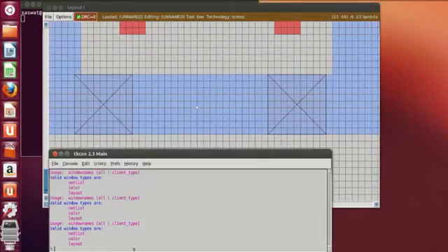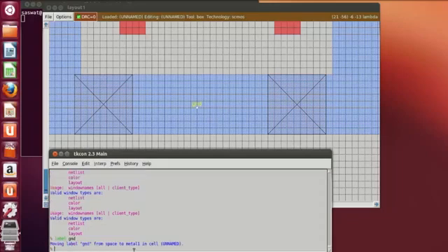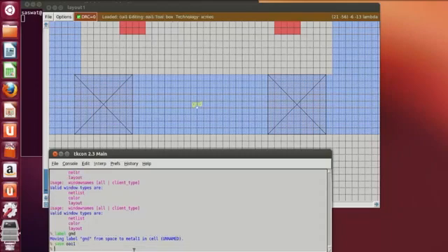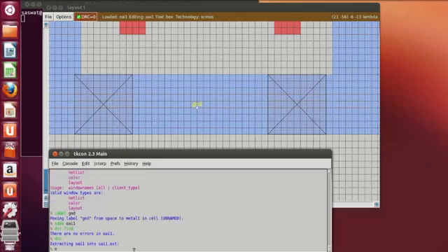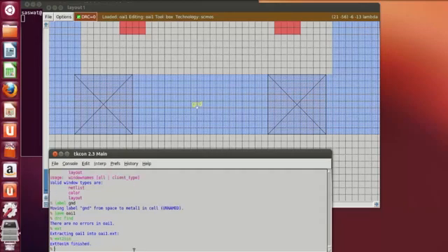This is ground. Now you can save this as Or and Invert 1. You want to find the DRC errors. There are no DRC errors. Then extract. The ext file is generated. Then extract to sim. Then extract to spice.